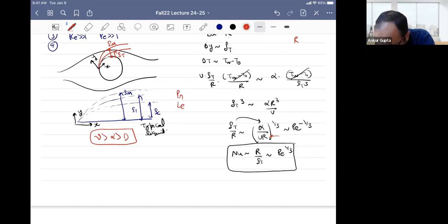Lewis, and there was another one, the Schmidt number. These three we had discussed back, and so these are just typical liquid properties. This is not something that we have derived essentially. People have measured it, and it turns out that momentum diffusivity is much larger than alpha, much larger than D for liquids. For gases, they're all the same, which makes it a mess to solve a gas flow.